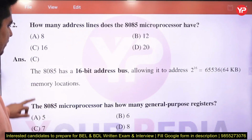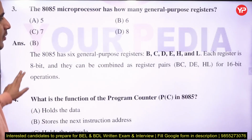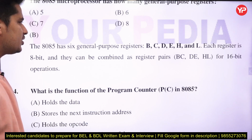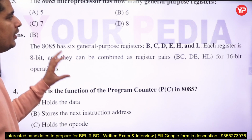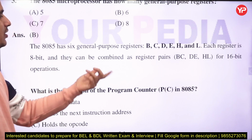The 8085 microprocessor has how many general purpose registers? There are 6 general purpose registers, that is B, C, D, E, H and L, and we can use their combination. They are separate 8-bit registers, but if required, you can combine them as the pairs BC, DE and HL.